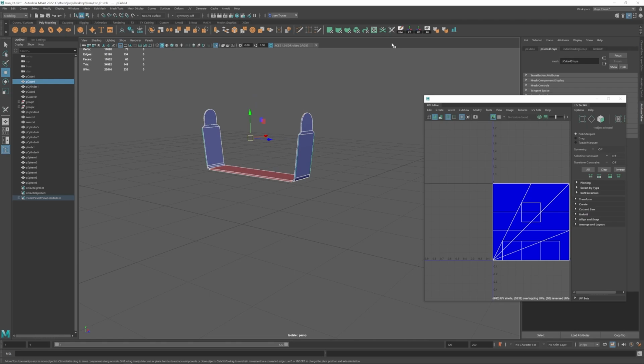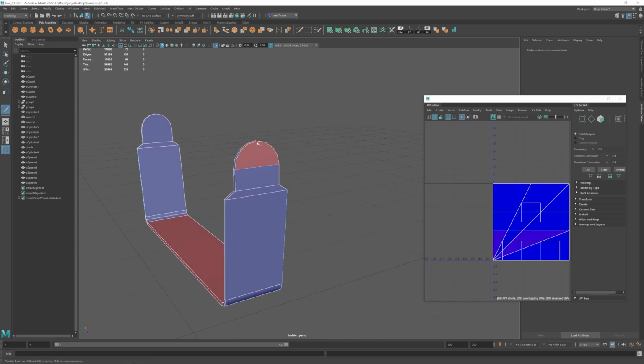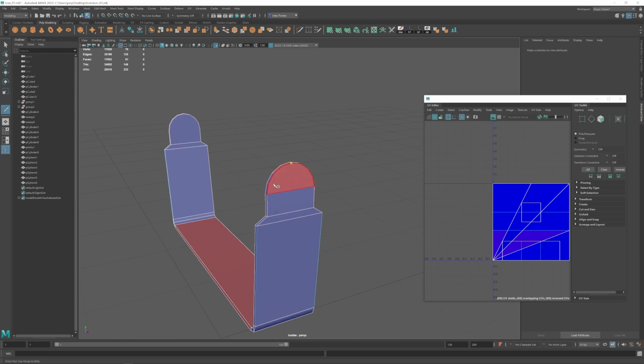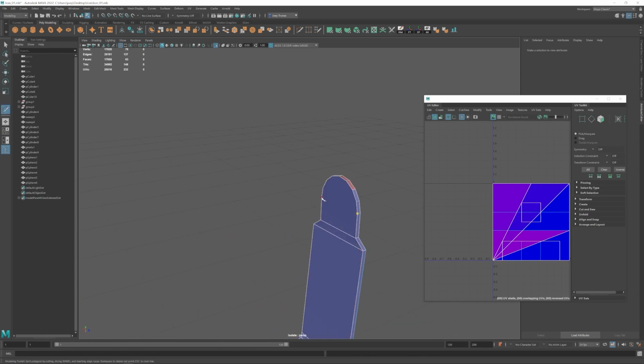So for the rest of the UVing process, it's going to be the exact same thing for every shape. I'm going to start off with deleting history, freeze transformations, and center pivots, so all that history is removed. And then I can go in with that multi-cut tool and start attaching vertices so I have no faces that are more than 4 sides. And once the shape is looking good, I can then UV it.